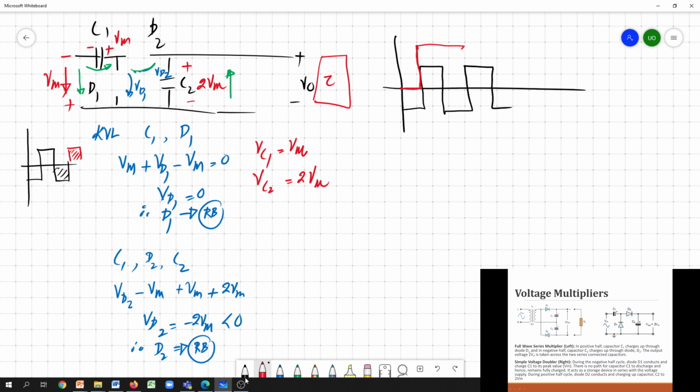If you maintain a high time constant, then this C2 acts as a source for the external circuit you plug into the output side, because your input is now simply isolated from the circuit. So the output never changes depending on the input. Anything that happens to the input does not affect the output side, because these two diodes get reverse biased and decouple the input from the output.